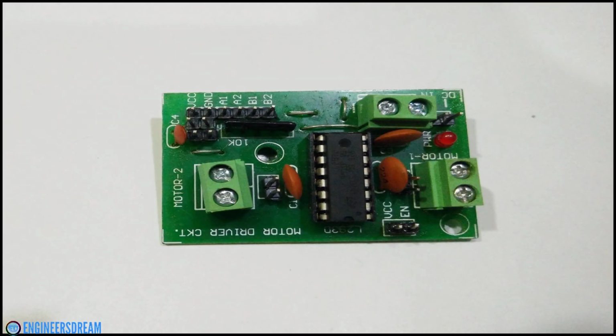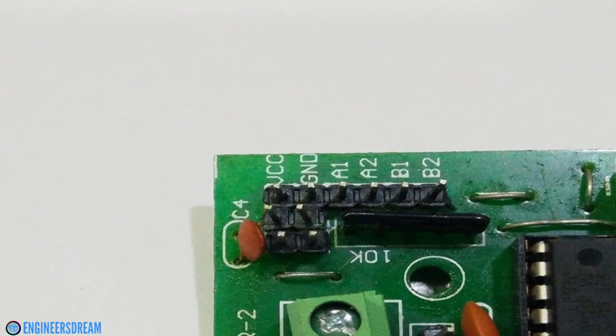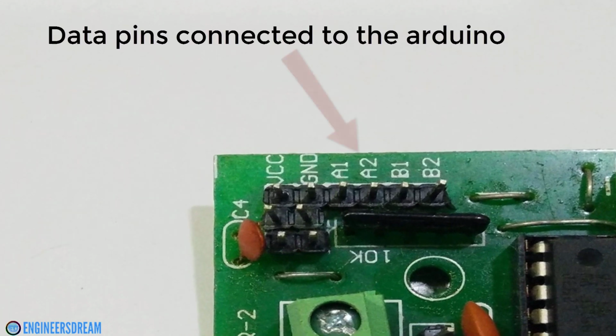Now if you look at the first motor driver, then it consists of 3 green sockets, 2 at the bottom and 1 at the top. It also consists of 4 data pins on the top left side. The input pins of the L293D motor driver IC, that is pin number 2, 7, 10 and 15, can be accessed from the top left side over here at A1, A2, B1 and B2. To these pins, we will provide inputs from the Arduino's data pins.